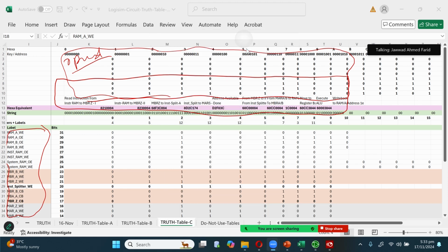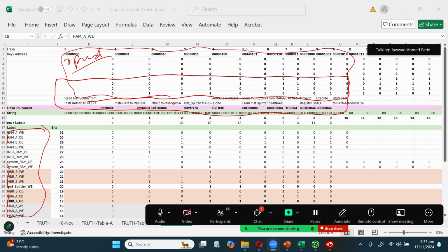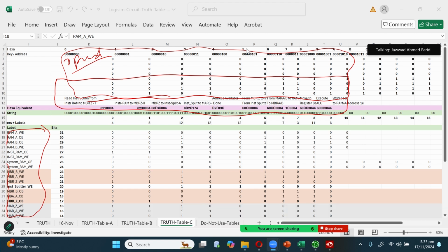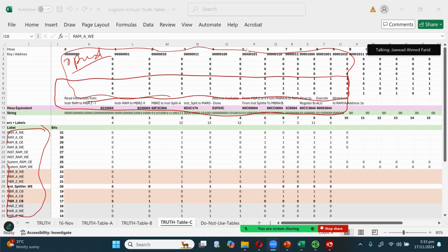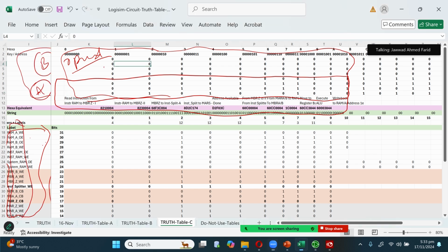If fetch remains the same, what will most likely change is that you would, for example, rather than just having one operator, let's say if I have the ALU where the data is going, I would have to tell the ALU this is the opcode, so please perform this specific operation. And then the ALU will then react and respond accordingly. So there'll be maybe 1 or 2 signals that will change. And how do I know what to do when? So as long as I understand that, let's say, if I change this opcode right now, this opcode is 0000. Let's say if I change it to 1111.